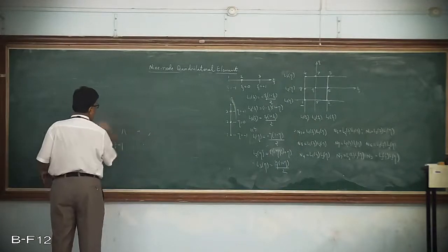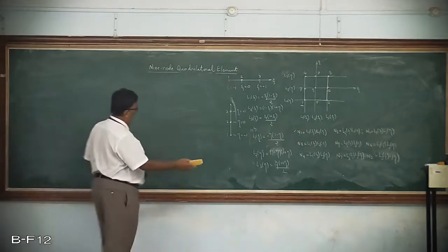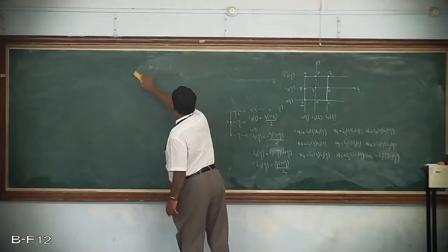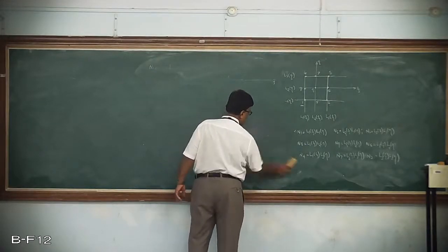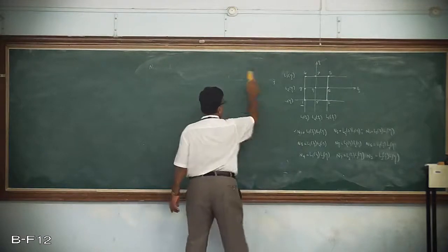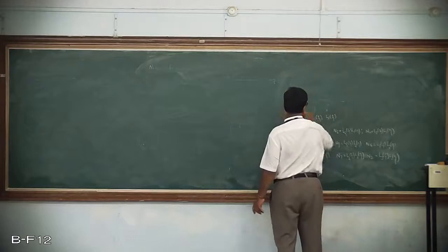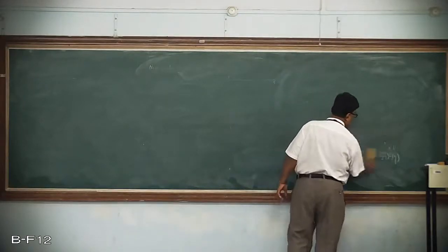Here, only the shape functions are sufficient. Other things we can routinely find out. Maybe the amount of calculation is going to be little large, but the procedure for finding the U matrix, strain matrix and stiffness matrix and all other things will remain same. Only we need to define the new shape functions for all these new elements, higher order elements we call it.